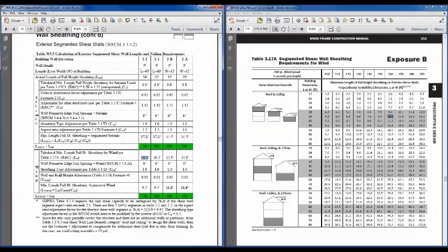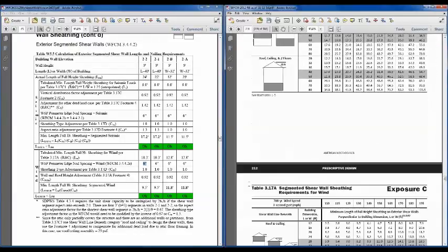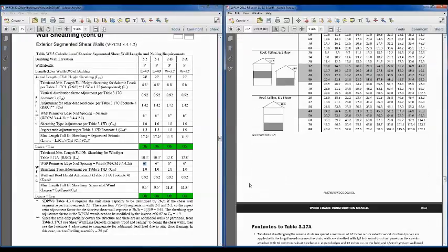There is no sheathing type adjustment because that is going to end up being enough shear wall. We've got 24 feet, so we've got plenty. So we're not going to have to reduce our nail spacing at all. We'll do that on the first floor, and you'll see how that works. Our roof height adjustment factor, we looked at something similar to that earlier with seismic, but let's take a look at the footnotes to these tables on page 213.